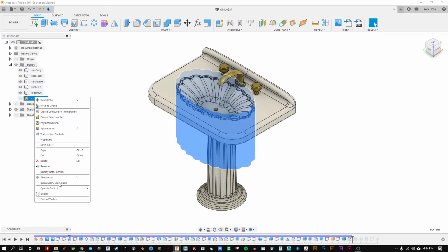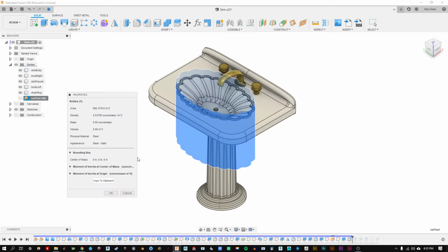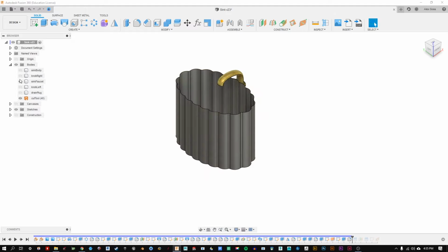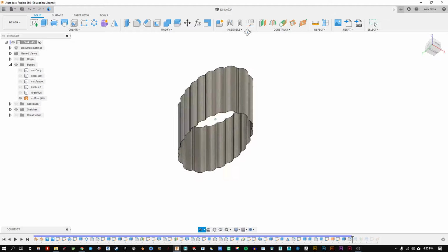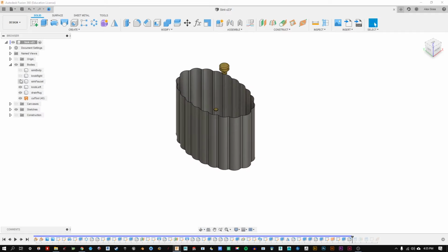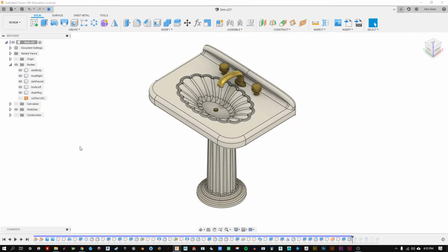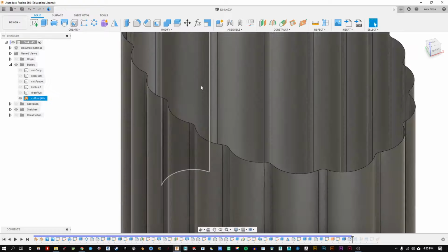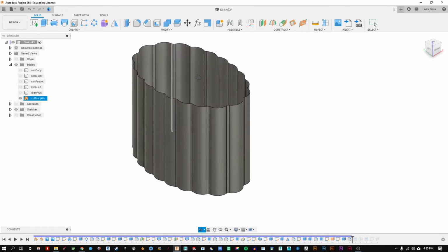It's pretty cool. If I click on this other object that has this little orange open loop, you can see it's a little bit different. It doesn't have a center of mass in this case. Now, why is that? If we isolate it from the other objects, we can see it looks kind of like a cookie cutter. And this object is infinitely thin, but it does take up space. So it's not watertight. It's not a solid object. All of these other objects we're looking at are solid, whereas this cookie cutter shape has no thickness. So we call this a surface.